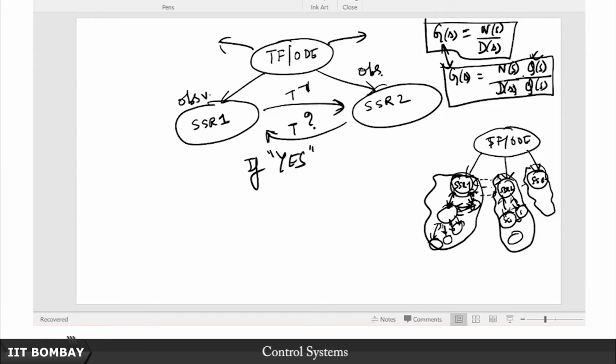But I just want to make sure that you understand, when we say it's the same transfer function, we mean exactly the same transfer function. So we are not cancelling out some factors that you are not cancelling out, and I am not cancelling out some factors which you are not. We are basically dealing with the same poles and same zeros, and the same constant gain. Only then do we call them the same transfer function.